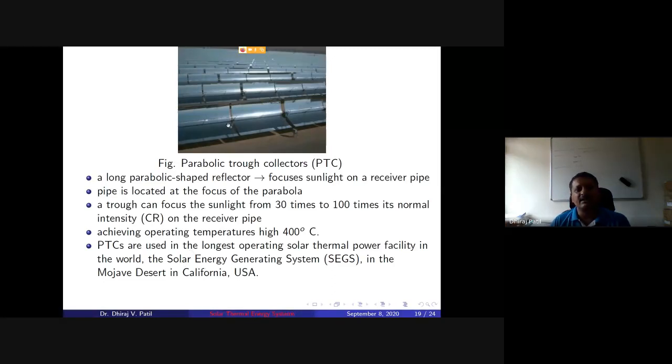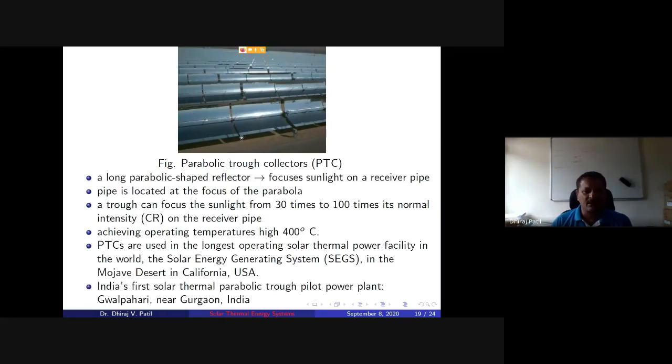Basically, you have to have a working fluid. That could be water. Nowadays, a lot of research is happening on what working fluid we should use. Should we use nanofluids for absorption? You need a large thermal conductivity for this, so to improve the thermal conductivity, people use nanoparticles, say carbon or aluminum oxide, Al2O3 nanoparticles. Al2O3 nanoparticles are commonly used, and then you can extract this energy from the concentrator.